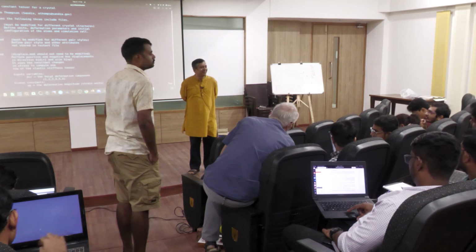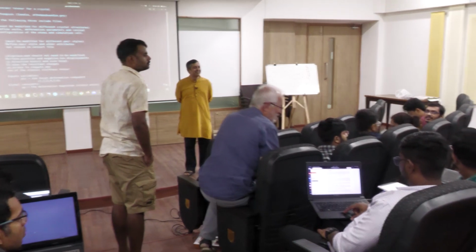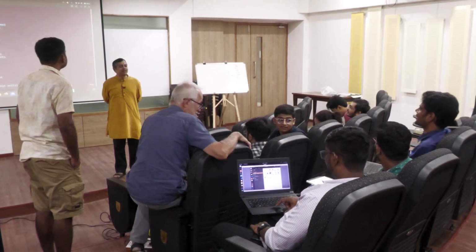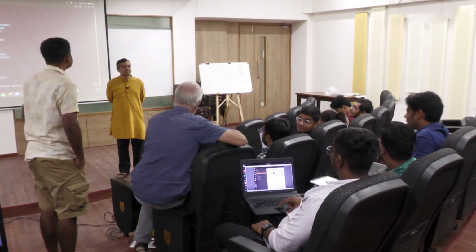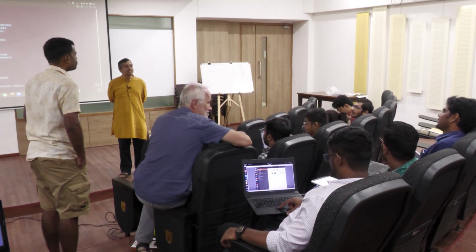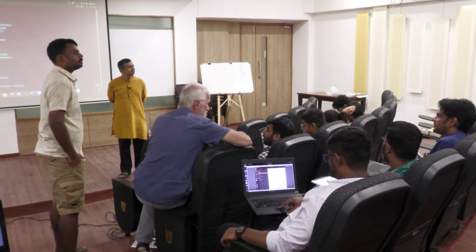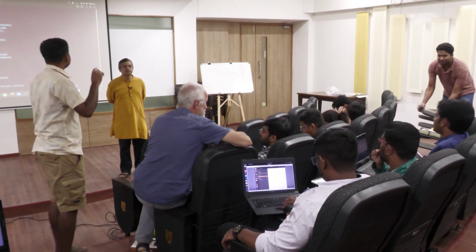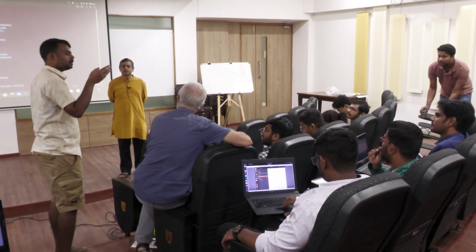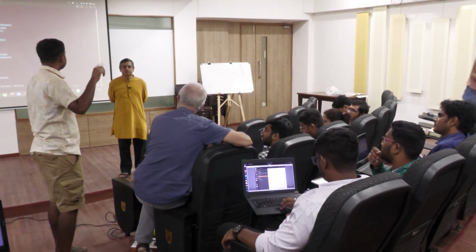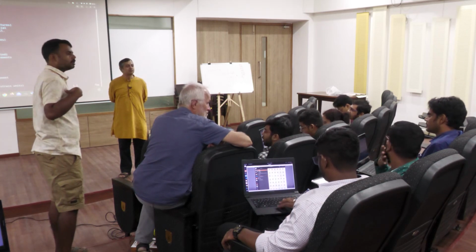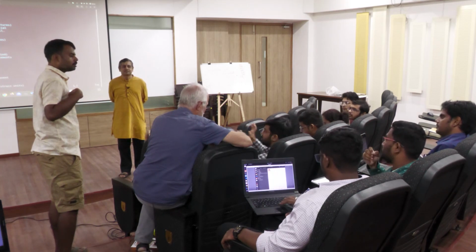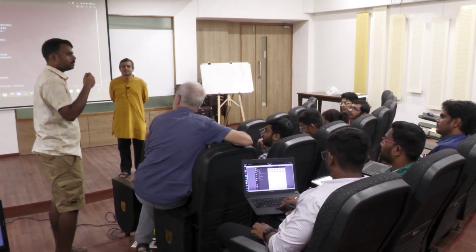So maybe this potential is not needed. Probably LJ will still work for you. No, for the EM potential, if the many body package is there, then it works, but that is not there. That is what it is complaining about, right? The many body package is not there, that is the error message, because that package is not compiled.